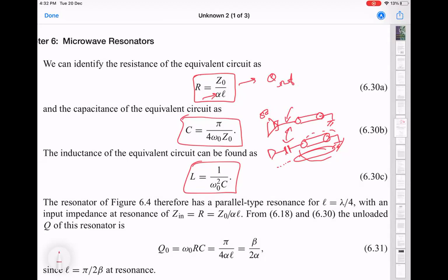We are just saying that near the resonant frequency, there is a simpler model, which is that of an LC circuit with some effective L and effective C. So that approximation is perfect as long as the frequency you're choosing is not too far away from the resonant frequency of that resonance. But that's a very natural approximation to make because if you are making a resonator in your experiment, you obviously want to work near the resonant frequency, right? You're not going to be working far away.